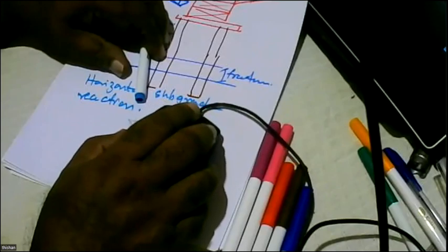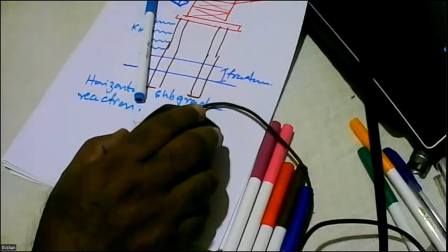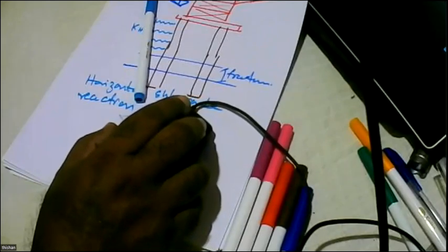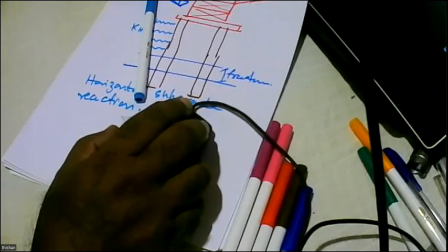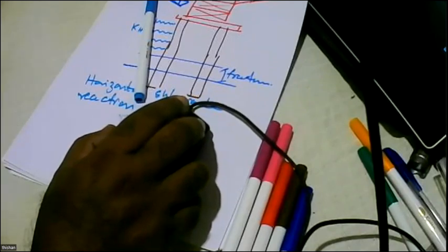Sometimes when you have clay soils, they may not be fully of laterite origin. So you might find they are really weak soils, like SPT less than 2 means it's very bad soil. But you might get SPT of 2 to 4, again pretty bad soil, but not the worst.